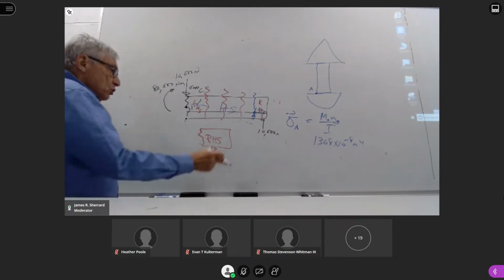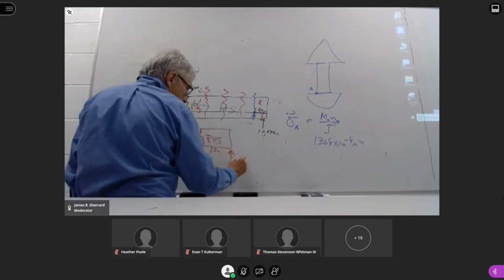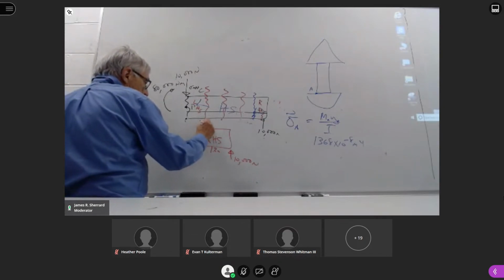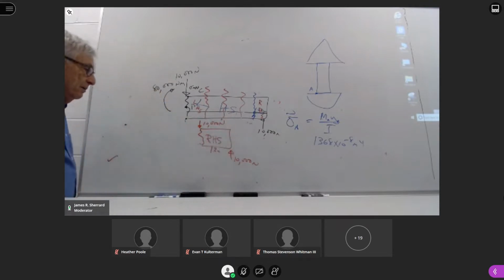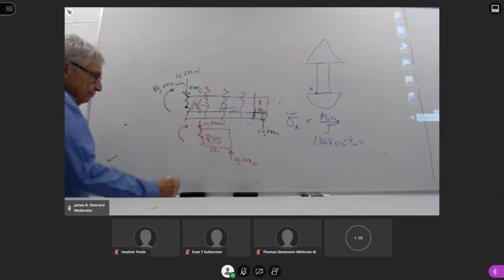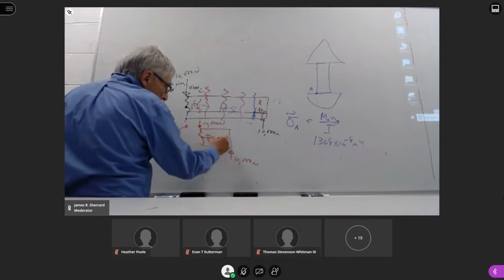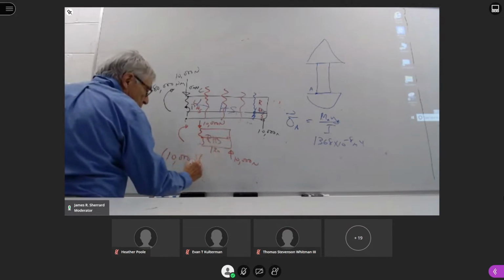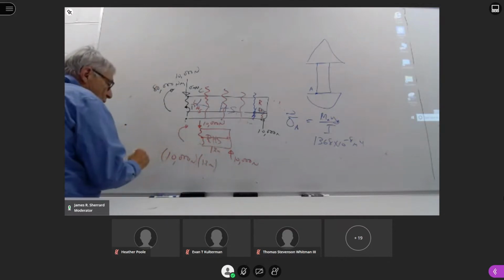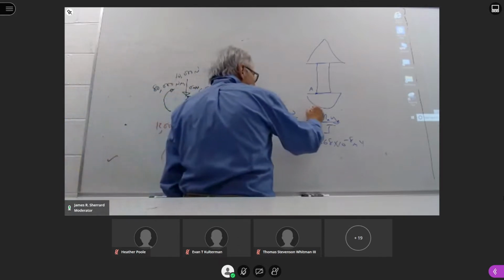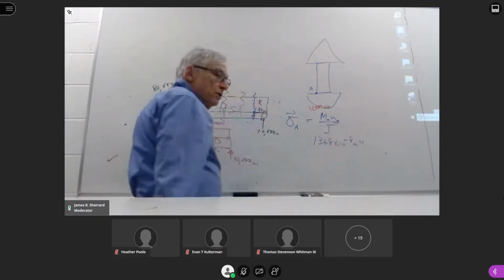You draw on, again, any given forces, moments, torques, couples you have. 10,000 newtons. To complete your free body diagram, you know that this guy has to be acting down. Okay. Again, this makes it want to go counterclockwise, so we know we're going to have a moment here going this direction. If we put our finger in the cut, this one creates no moment, but this one, perpendicular distance, it's going to be 10,000 newtons times 1.2 meters. That is its moment, so that'll be 12,000 newton meters. So I can go back here, this value is 12,000 newton meters. Okay.